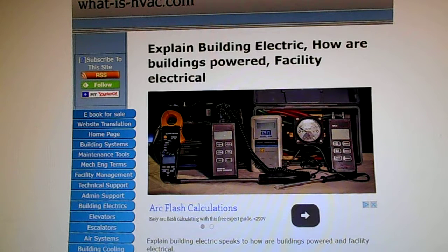Also in North and South America, it is common that a single-phase 220 volt or 230 volt residential and light industrial service is provided. In our homes, the 220 single phase is used for our dryers and stoves. There are a few substations per area which supply the 220 volt or 230 volt power as a hot wire, and neutral is connected to the building from one phase of the three-phase service.